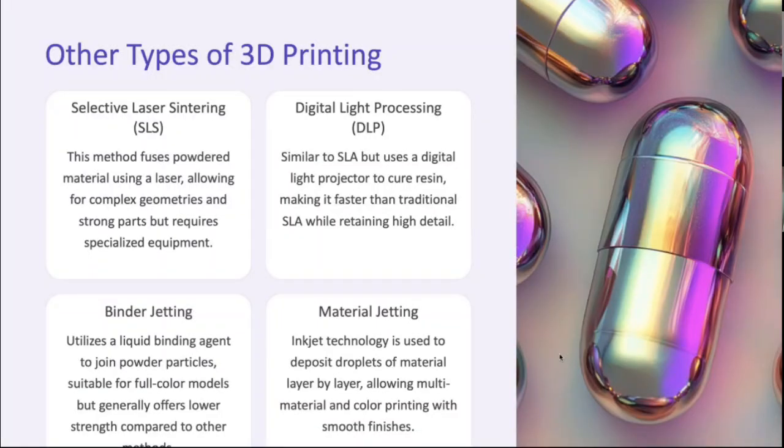Like, we can even print plastics and other materials, but metals can be printed very easily by using this material jetting technology. To print the metal, you will have a nozzle, the same as our FDM 3D printer. There, instead of filament, we are using metal powder, or ground metal. Sometimes a plasma torch is used, or sometimes some resistance technology, such that the powdered metal will be melted and deposited wherever it is required to make the required 3D part.